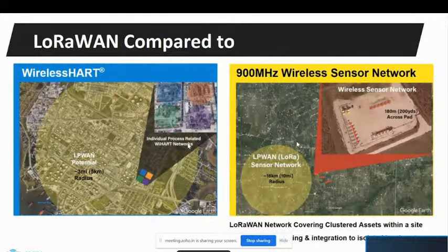If we have a very high data rate, low latency system, it can communicate via WirelessHART, and if we have remote sensors with a low data rate, they can use a LPWAN standard like LoRaWAN. So both can coexist in the same plant.